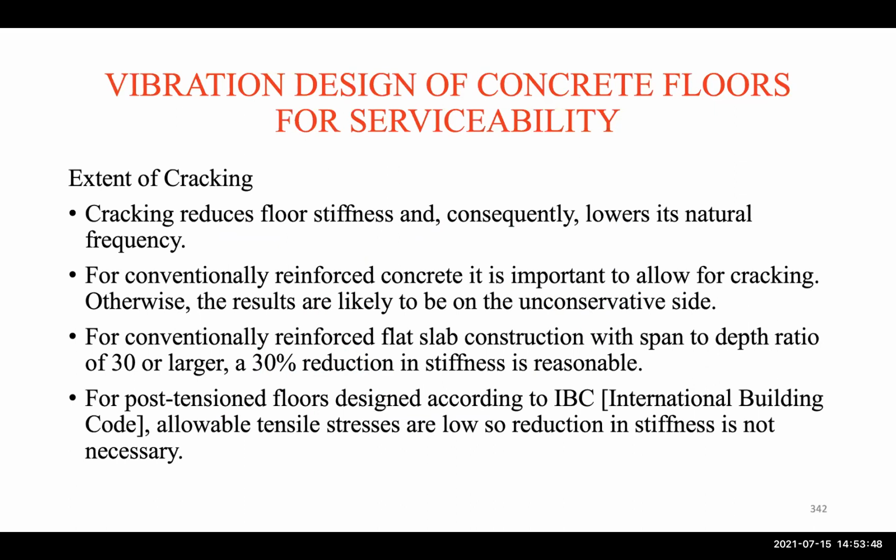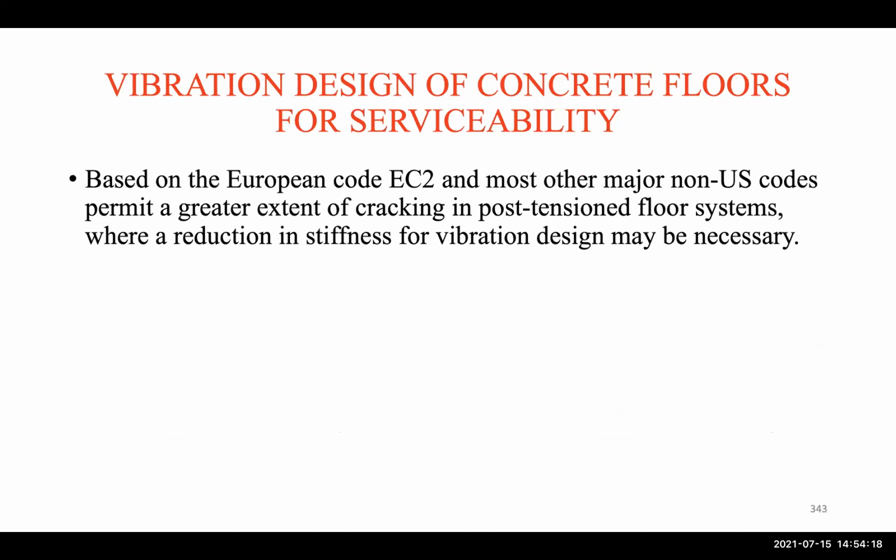And then the extent of cracking. This affects, of course, if cracking is there, then the moment of inertia is less. Then not all the concrete is effective, and then we may have an issue. Now we don't have that in PT floors, considering their very low stiffness, because the limit for tension in concrete floors is small. So even if there is a small crack, we can consider it as a gross cross section, as we talked about in deflection.